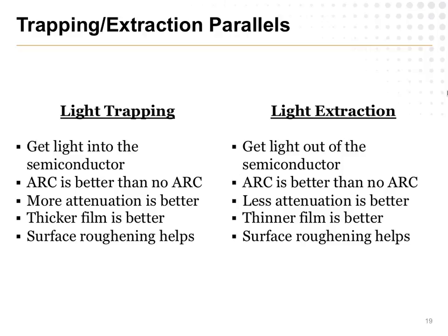In light extraction, thin is now it. We want to be as thin as we possibly can, so we get as many bounces as we can get out of it. Again, there's only so thin you can go before the thing is physically, mechanically unable to support itself. But people have probably thought about that and found ways to get around that problem. And in both cases, we found surface roughening absolutely helps. Rough is good. Flat, planar surfaces, as a general rule, are pretty bad, and we don't like them. It's neat how some design principles stay the same, but others completely trade places.